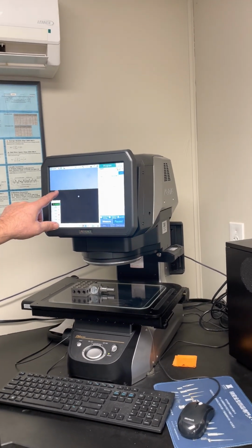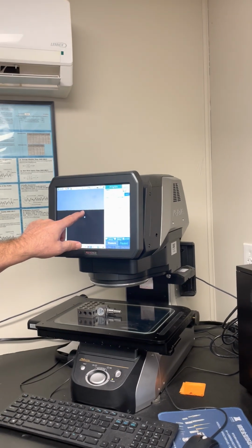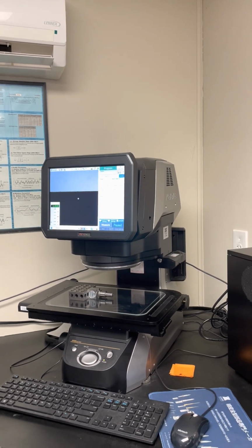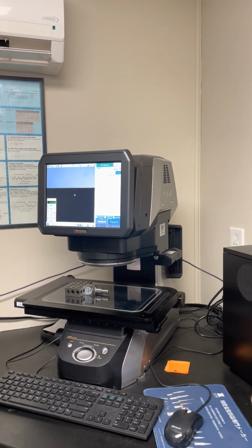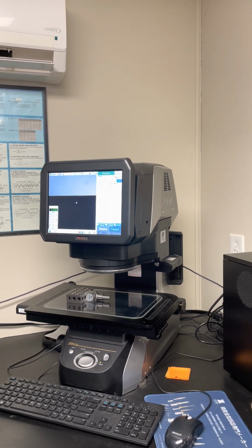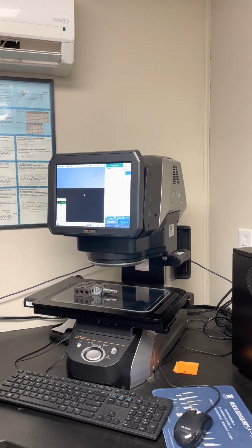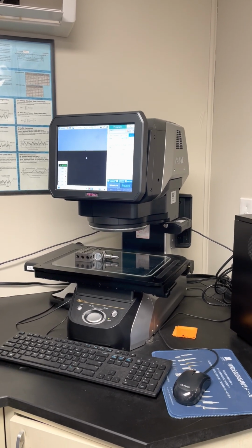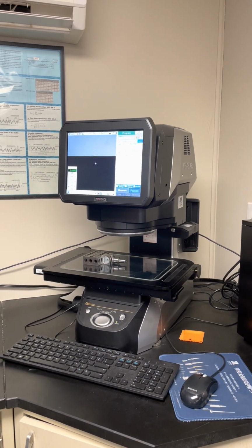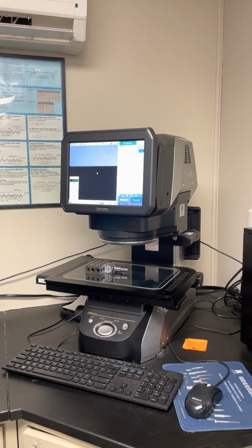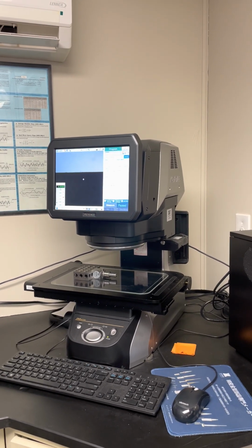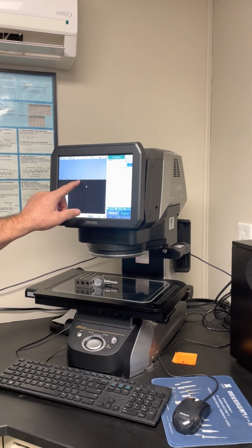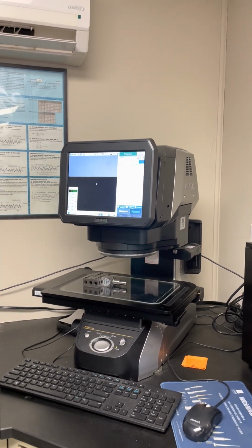You'll notice a couple of these points are in red, because when it creates my straight line, it's also looking at the straightness of that line. If the system deems that a few points are outside of a straight line calculation, we're going to exclude those. So you don't have to worry if there's a scratch on the machine or something of that nature. In this case, it sees a couple of little hiccups right there, which is fine.